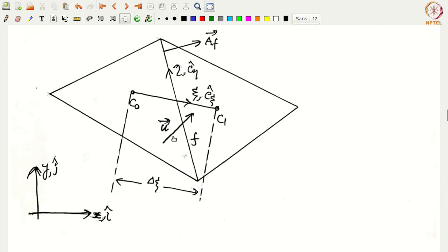Okay, so if Ff bar is positive, essentially you can move this arrow here. If this is going this way, that means it is in the direction of Af bar. That is the only way it can be positive. Then what will we take? The phi value on the face, we would like to take as phi 0. If it is going this way, then we would like to take the phi on the face value equal to phi 1. That's what the condition says now.